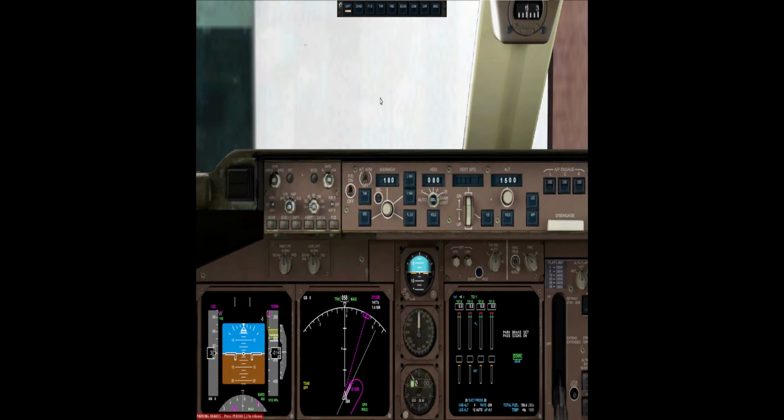Next up, we're going to be taking off on 9 right, so we need the heading for that runway, which is 90 degrees. Set the bank limit to 25 so it'll actually turn properly, and set this to our initial altitude, which is 6,000. Now next we will set the barometer reference.